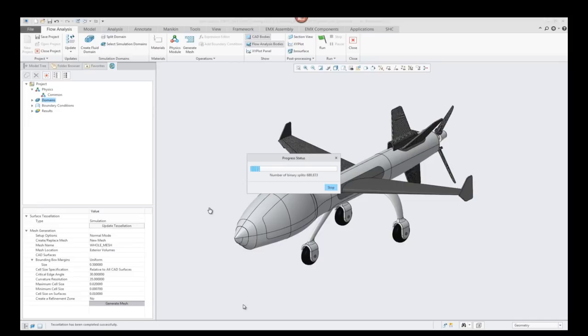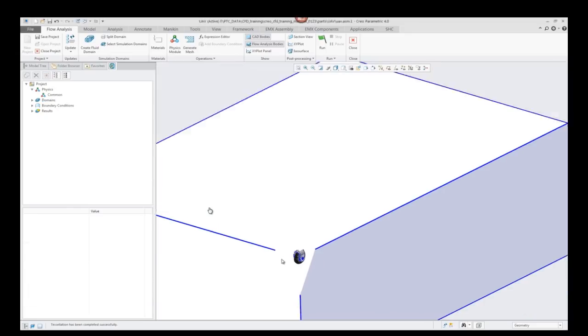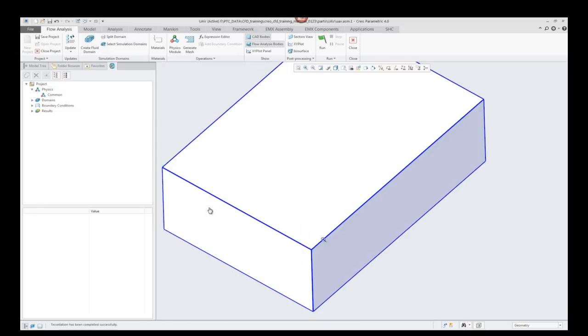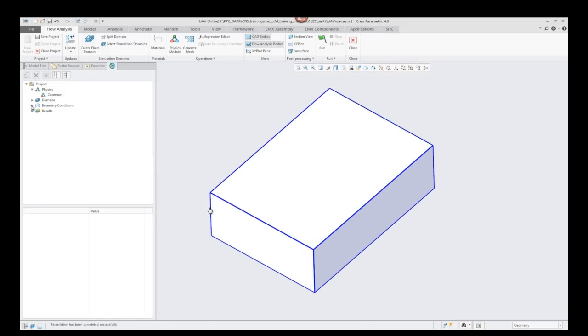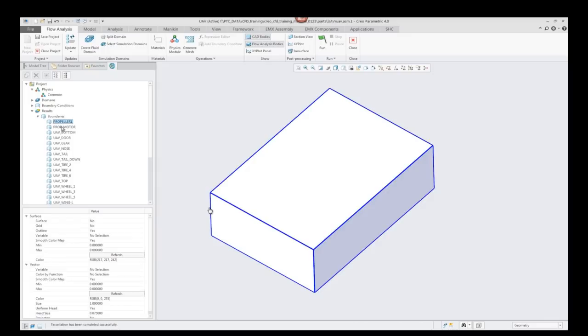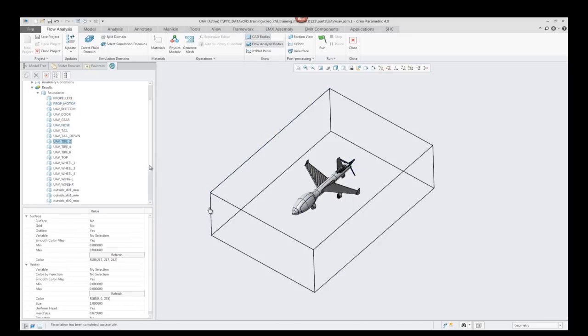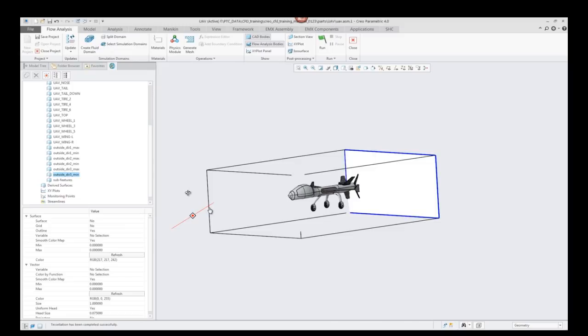So this is creating the cells now live. There's no editing to the recording here. This is as it actually ran. So it's creating the cells, checking the faces with respect to the geometry, and then building the mesh off of those cells. And here we go. This is the hanger, effectively, that sits around our plane, and these are all the plane components within it. So you can see this is the mesh that's just been created in our results section of the model tree.